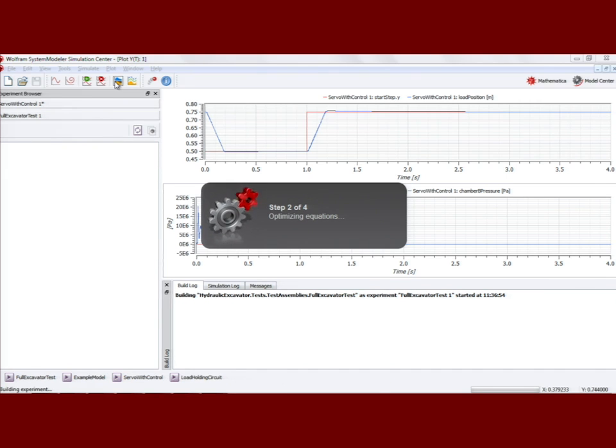We build this example, and when we simulate it, in a while I will show a new feature. While you're doing this building process, converting it to C code, you have to wait for that to finish before you can do anything else. You also had to wait afterwards, when you started to simulate, until the simulation ended before you could do anything else. It was locked. It would lock the software for any other operations.